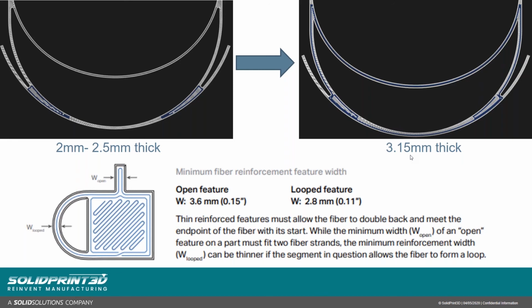It's not just about the actual design itself, it's how we can think about the printer during this process. If we can add in 45 degrees in different areas, if we can think about maybe using a teardrop shape rather than just a straight circular cut, we can ensure that no supports are being required. If we are going to be looking to use a Markforged printer, for example, we could go in and just increase thicknesses slightly in some areas, just so we can put in that extra strength with the continuous fiber itself.